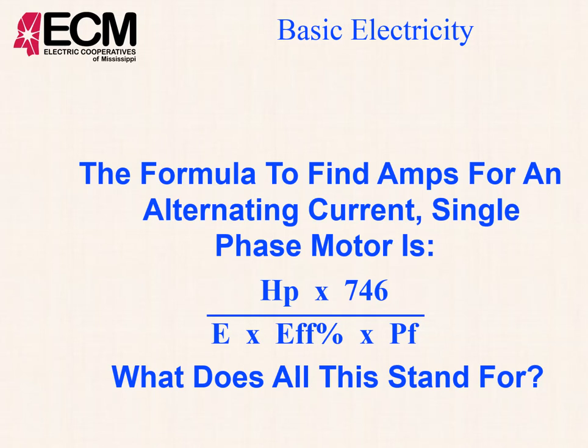And then also there's another little something there, the PF, the power factor. Not going to get into that too deeply today, but the power factor is basically whether our voltage or our current is leading or lagging. That has to be accounted for as well. Now, when your air conditioner cuts on in your house and the lights dim down, that's because the current has outrun the voltage.